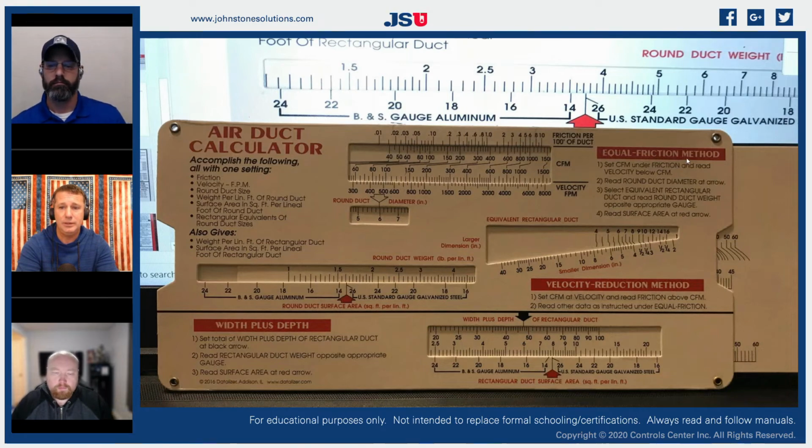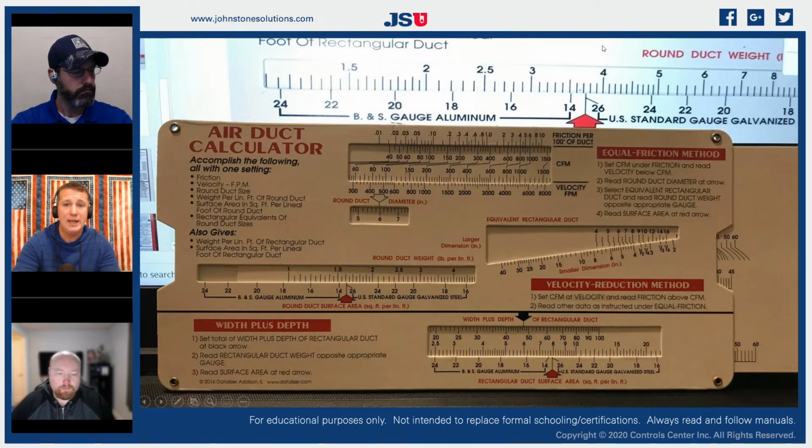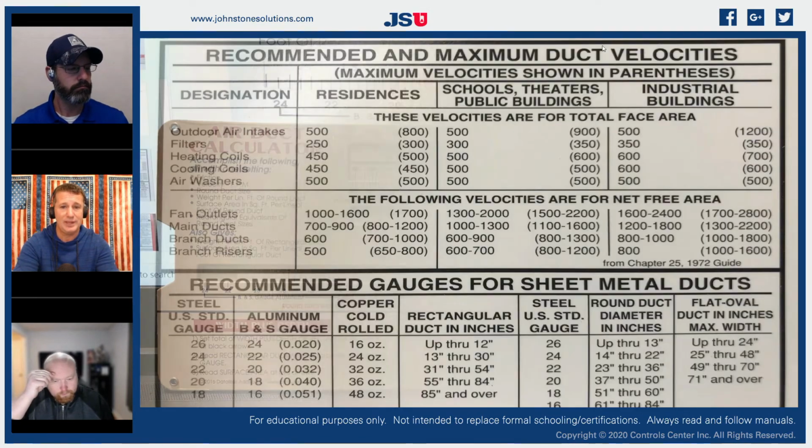So it's just a different mindset when we start looking at duct calculation and static pressure, because we can't say a 6-inch is good for 100 CFM. We can't say that a 10-inch is good for 400 CFM. We cannot use those. Those are just rules of thumb. And as our static changes, so does the airflow. And the length of our ductwork is going to be a huge factor as well. So we have additional charts that help us out with that.